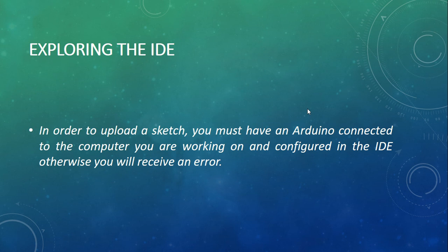So this is a very important rule that you must remember. In order to upload a sketch, you must have an Arduino connected to the computer you are working on and configured in the IDE. Otherwise, you will receive an error. So this is very important. Before you upload a sketch, make sure first the Arduino is connected to the computer you are working on and configured in the IDE. So that's very important.